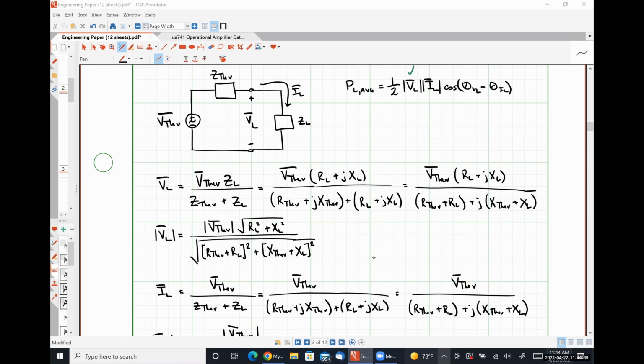So if you look at the end of our lecture for April the 13th, which I believe was the one we had right before Easter when we were talking about impedances, we could have a polar form representation of impedance where we simply had a magnitude and a phase angle, or a rectangular form representation of the impedance where we split it up into its constituent resistance R and reactance X. Reactances arise whenever we have capacitances and inductances.